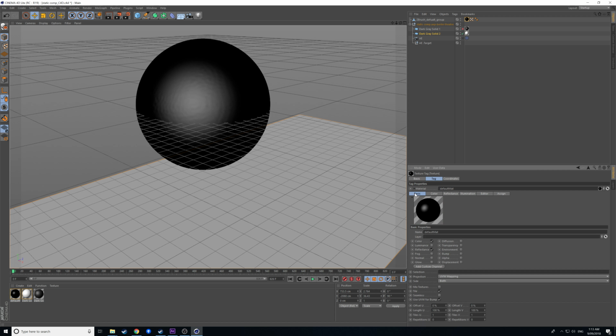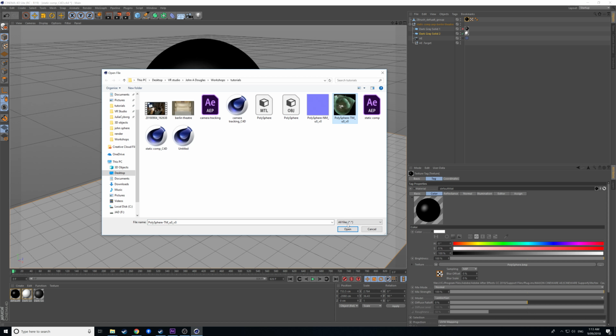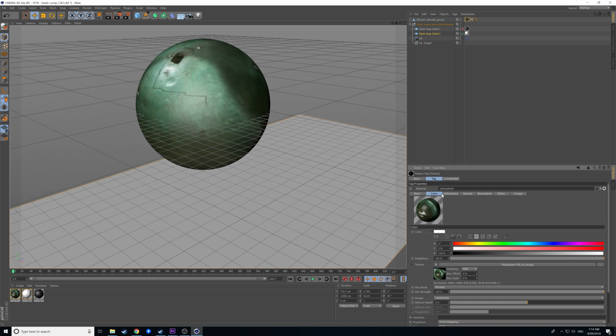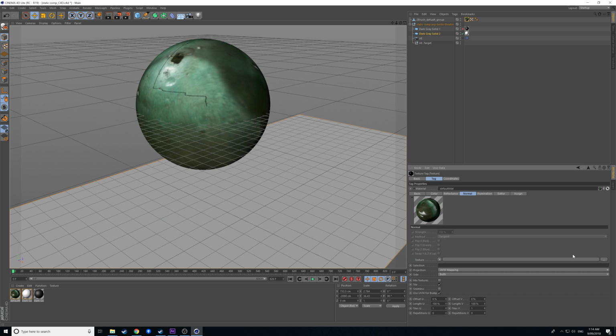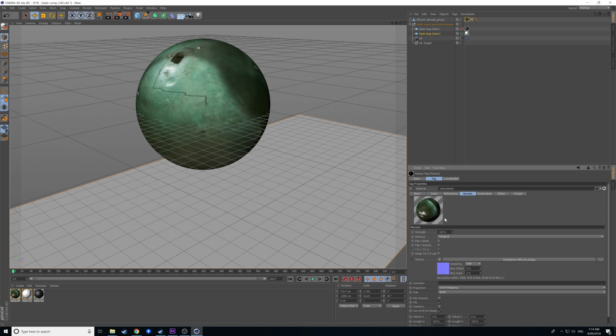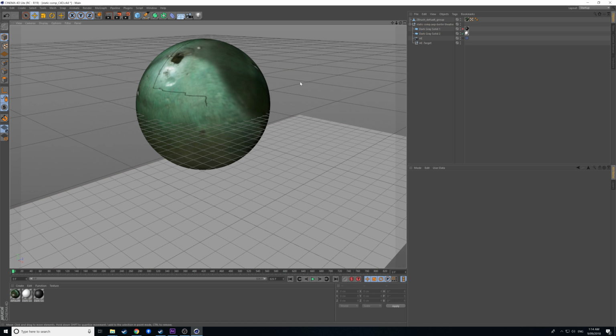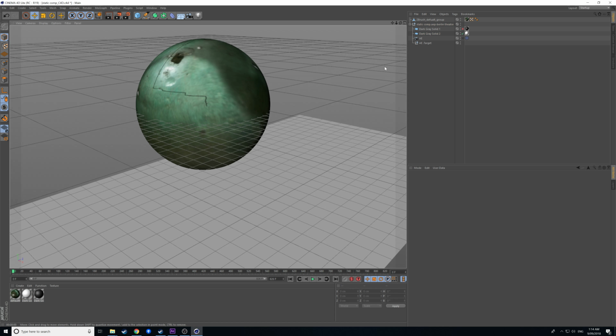So like before, I go to the material view, I'm going to add a normal map, and then we set up all of the details of the different texture maps in these different tabs. So I will set a diffuse, we'll reduce the reflectance, and I'll set up the normal map. And if we hit Control R, we can see what it looks like. Okay.